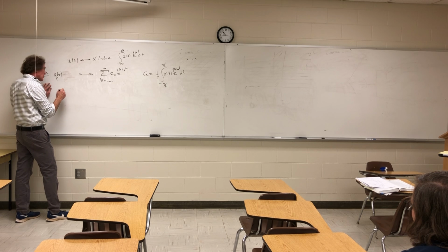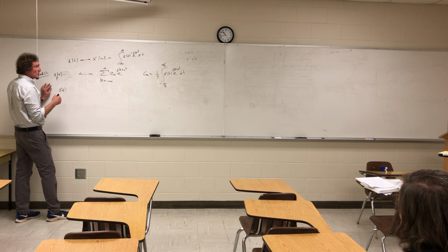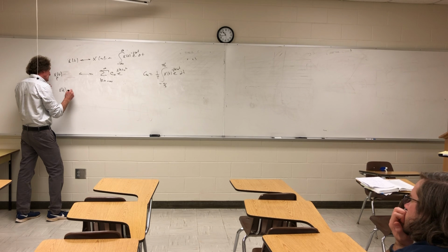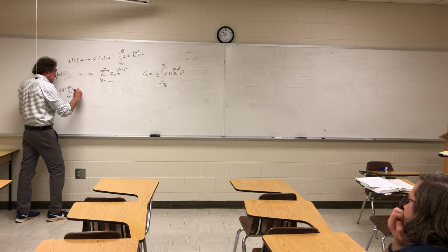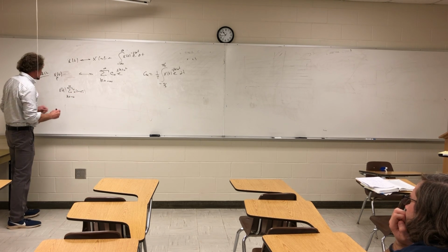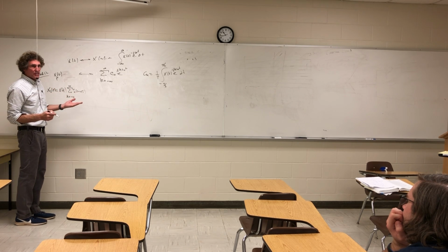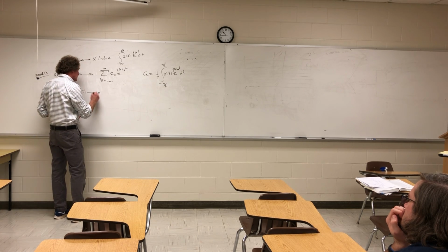Then we did something where we took x of t, right? And it could be chaotic or it could be non-chaotic and periodic. X of t, and we took this and we multiplied by a Dirac comb, and that's going to be the sum from n equals minus infinity to infinity of delta of t minus nT. So now this is going to be x sampled, right? And we saw, if we think about continuous time and what it's viewed as, then it comes over here as what?